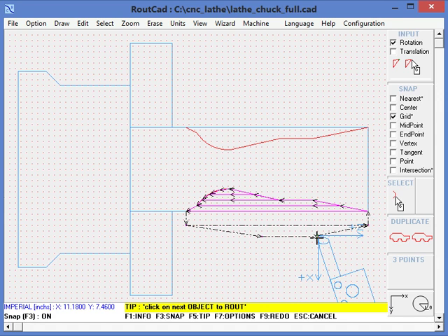Obviously, with the CNC controller, if the home location is over here and the CNC tool has stopped over there, when we reload the new G-code, even if we didn't go back to that location, the CNC, if it is working properly, will normally first move to the home location and then start machining, so there should not be a problem.